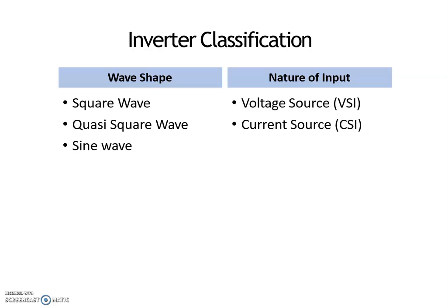That type of inverter is known as a self-commutated inverter, which does not require any commutation circuit. But if we incorporate thyristors as controlled switches, they require external forced commutation circuitry to turn off the switches.